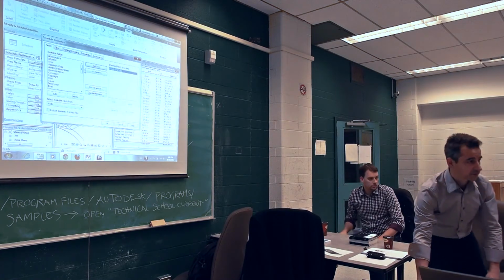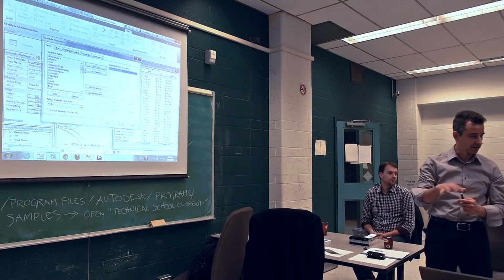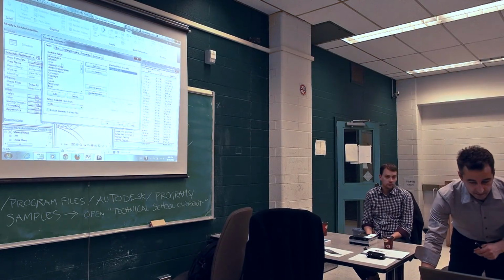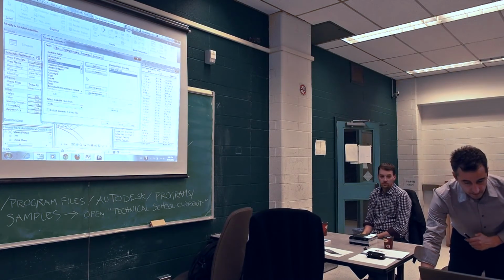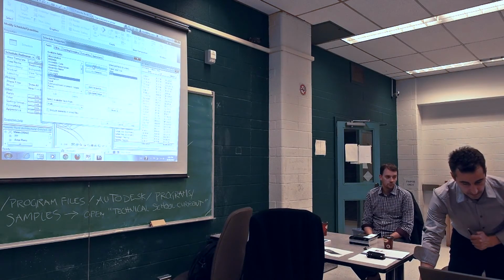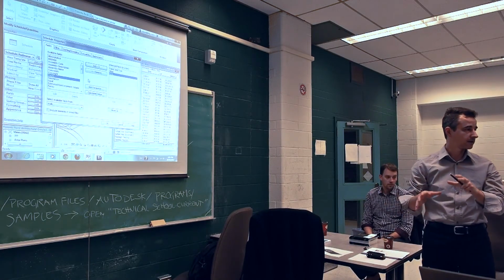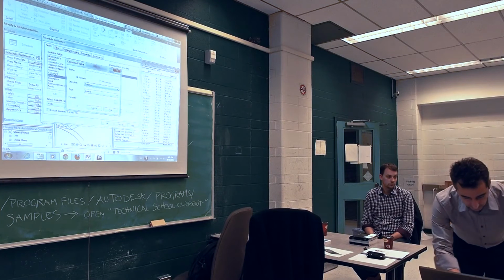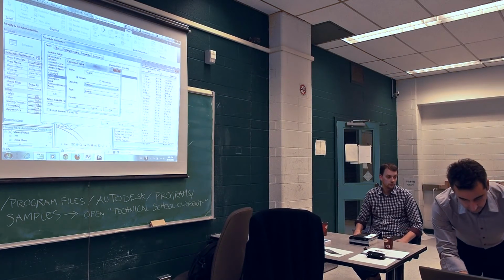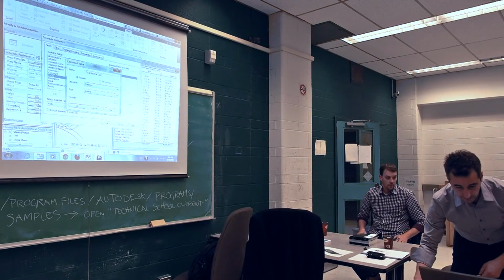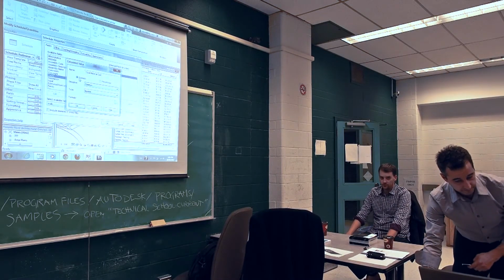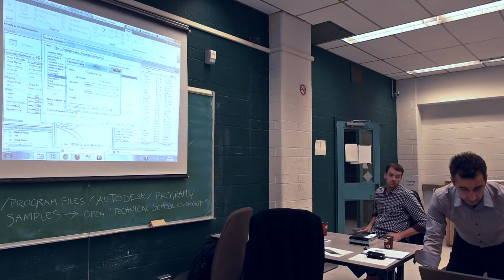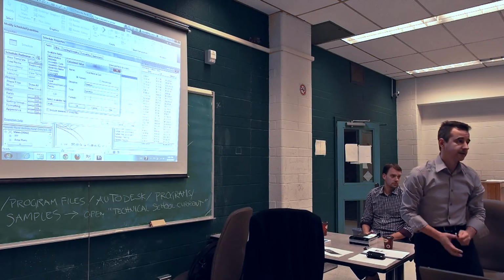I also need to do area. Generally speaking, wall scheduling is going to go around areas, right? You need the area. That's how you're going to price that. So you need the area. You also need the cost. And we know the total cost is not there, so I'm going to need to define a calculated value. I'm going to need to define that. And let's say, I'll call it total material cost. It is a formula. In the type drop down, I'll use currency because I know it's a dollar figure. And then in the formula, you can type.